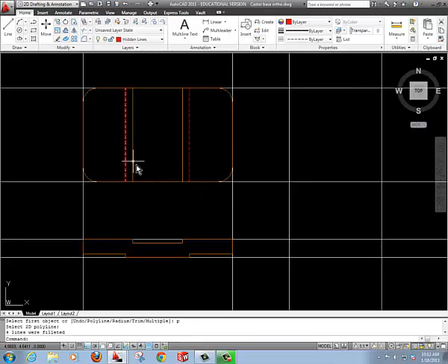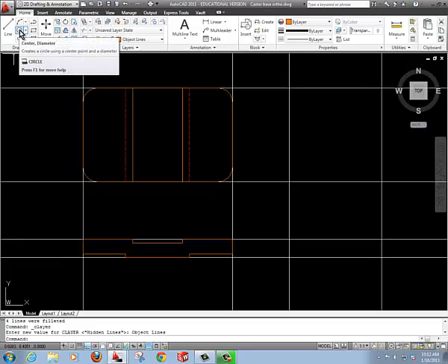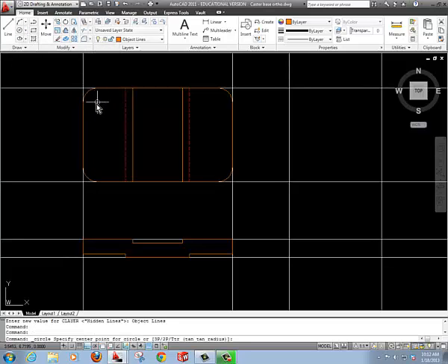We have our fillets. Now we need to draw our circles, and those circles will be viewed as object lines. So we're going to go diameter, and this one is going to have a value, diameter of 0.375. And we're going to repeat it along these by using the spacebar to terminate the command and spacebar to accept it again. So we have our features that are our holes.